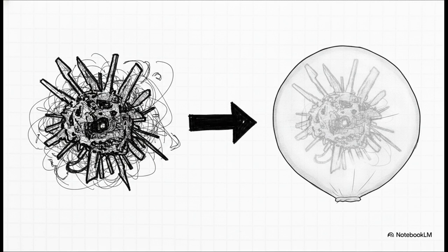You've got precise settings here. You can choose a really stable fit to surface or snap to edges to preserve sharp angles greater than 30 degrees. You can also tell the algorithm to allow complex tunnels or automatically cap tunnels to close off annoying little pockets and gaps. It's essentially a digital shrink wrap to save your simulation.